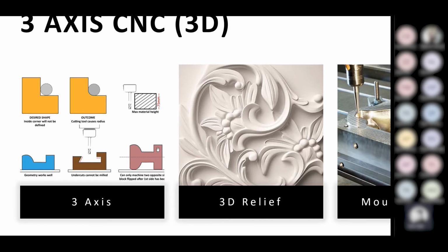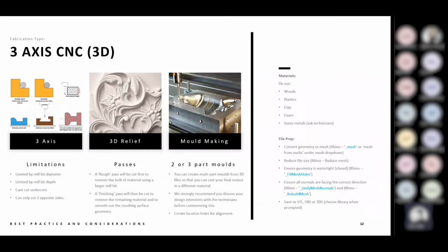Or alternatively, you could do a double-sided mill. So if you made like a frame around this object and had like a little strut to connect this object to the frame, it could cut it out, and then you could flip that over, and then you could mill the other side, as long as you can align it correctly. We don't recommend doing that where possible. Try not to do double-sided mills. They're really, really painful to set up, but you can get some great results.